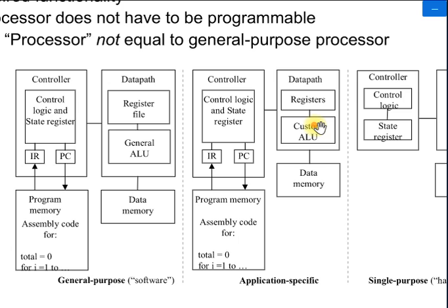So why do we use the custom ALU, not the general ALU? The advantage of a custom ALU is that it consumes less power, because the other power consuming items are not present. So this is the biggest advantage of the custom ALU.